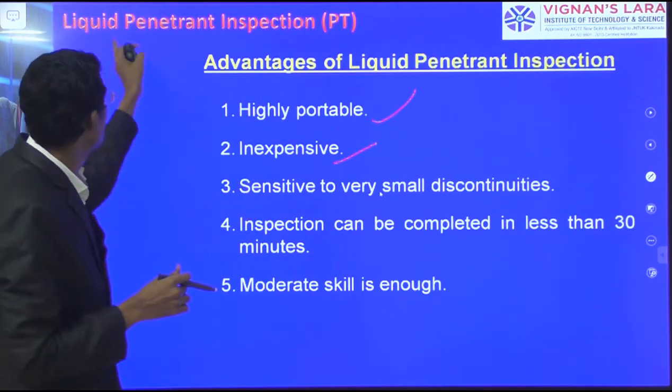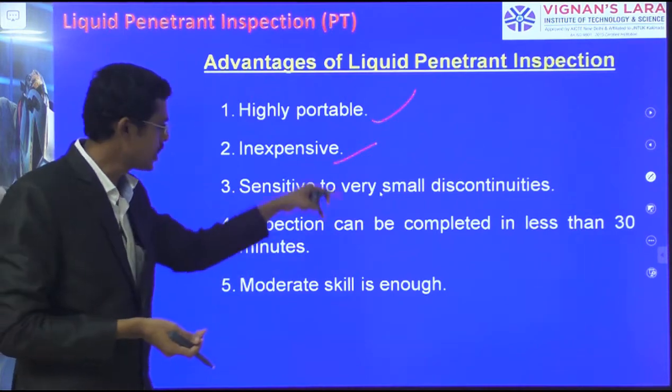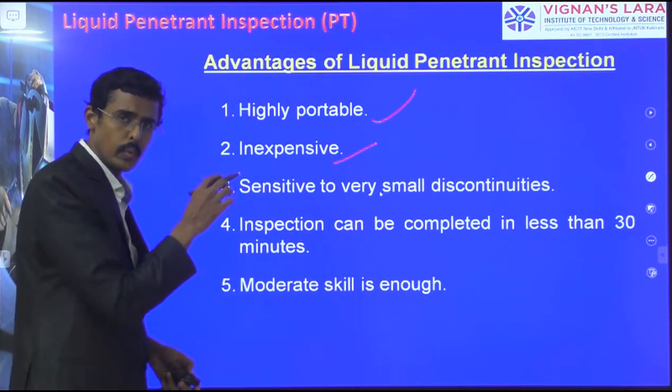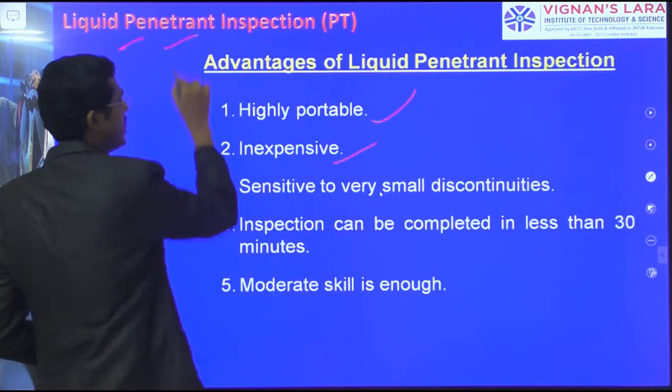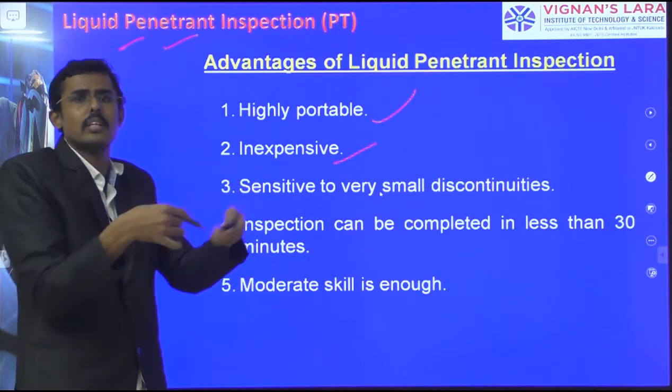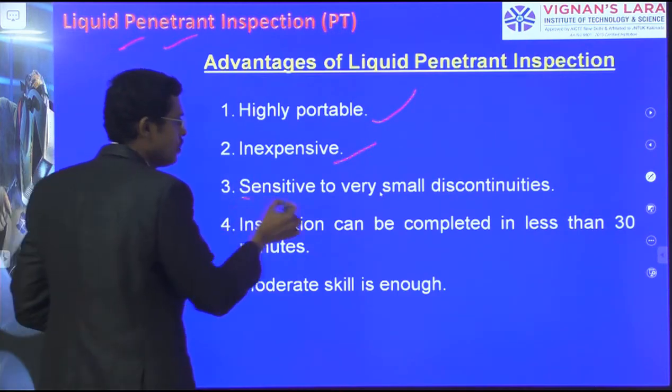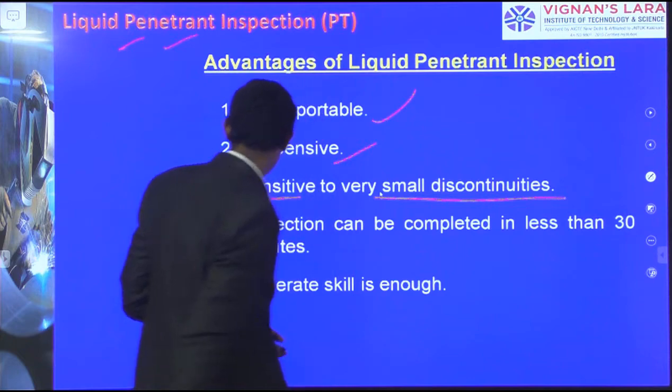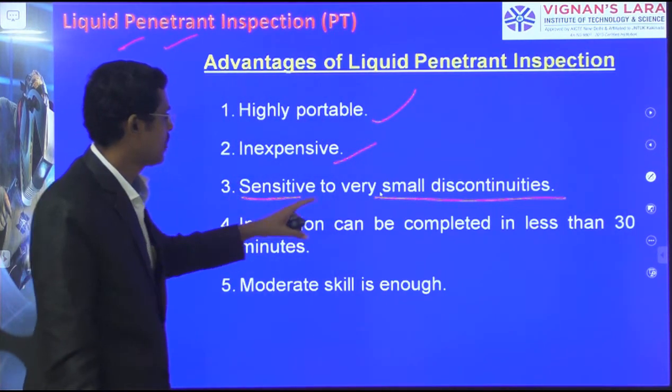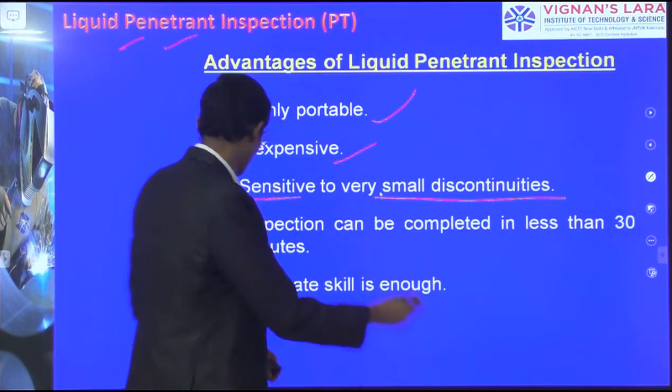But it is a liquid penetrant inspection. As the name says, liquid is penetrated inside, and we use the developer to extract it out. It is sensitive to very small discontinuities. Inspection can be completed in less than 30 minutes.